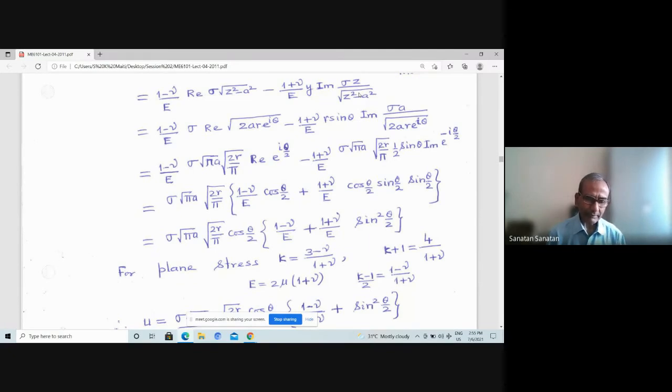You have two displacements in the 2 directions, u and v, or x and y displacements, but these 2 displacements have certain constraints on them, and that is what the compatibility conditions are. In terms of stress and displacement, you can write the compatibility equation, which can also be written in the form of stresses, and therefore that compatibility equation gives you an extra equation to link the unknown functions. That was used in overcoming the static indeterminacy in the case of stress analysis.